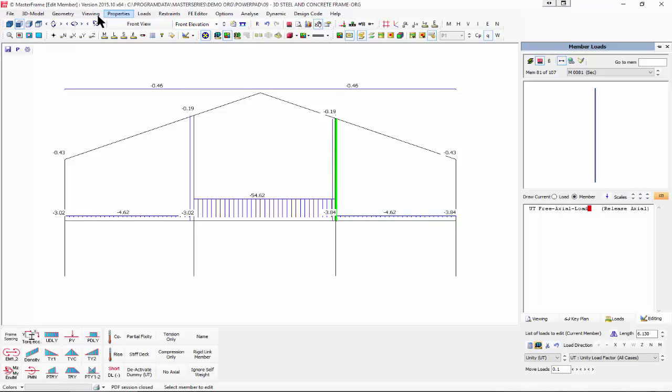Loading cases. Well, loading cases really comes down to what design code you're going to work with. So design codes, we have the British and South African, and more recently in the last 5 years the European, but with the built-in Euro norm and UK national annex values. So I'm going to work with the UK. You can create your own little annex and add it in if you're working overseas. Just change the 1 or 2 values in the table to do so. It's very, very straightforward. So I'm now said that I'm going to work to Eurocode.